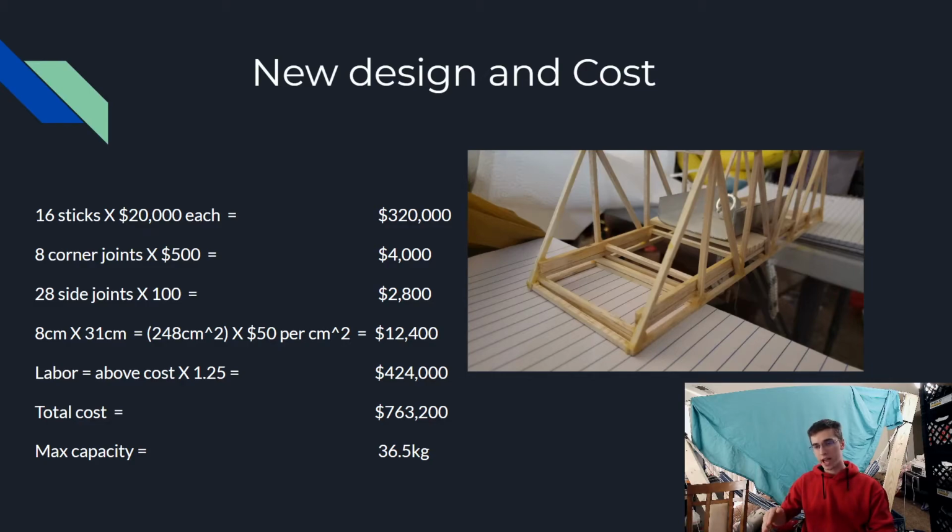You'll also notice that here is the bridge as it was after it's been destroyed. You'll notice that I put many more members through here to fully utilize the strength of the sides. In the first example, there were only 4 of these balsa wood sticks holding onto that single side piece. So of course those 4 broke, and then the single piece underneath broke. By having a ton of members here, it can fully utilize that side strength, and then by having 3 stacked on top of each other, that's where the majority of your strength comes from.